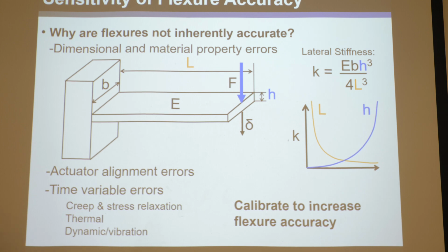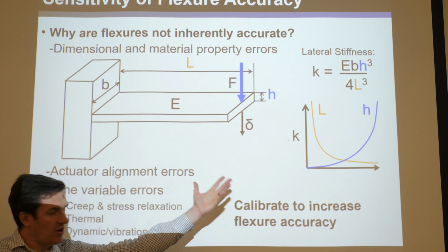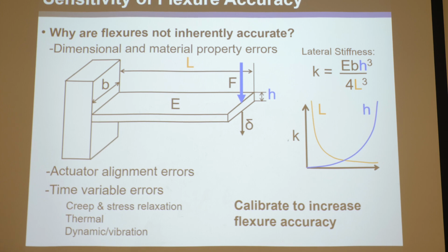You're not going to get it. So just make it the best you can. No matter how you make it, it'll be super repeatable as long as you don't yield it and follow the principles I taught you. And then just calibrate it. It's like telling the archer to start aiming in a different place. And once you calibrate it, it'll be both accurate and precise.